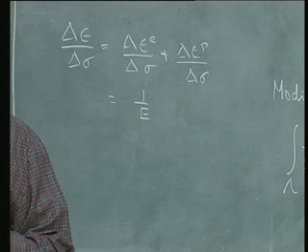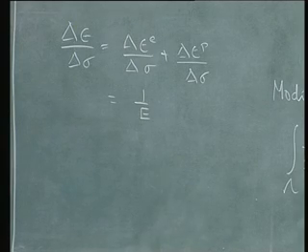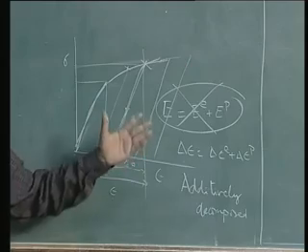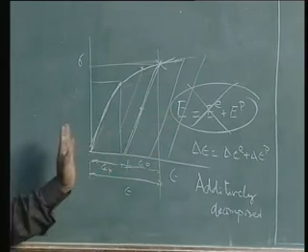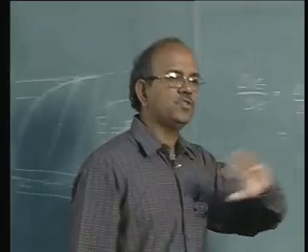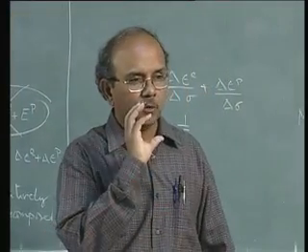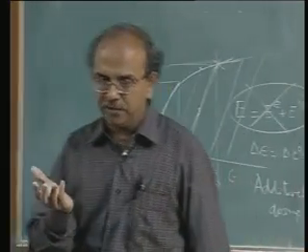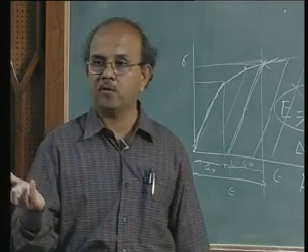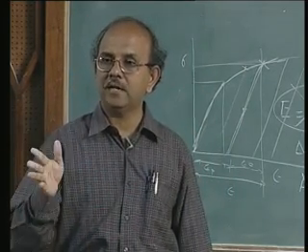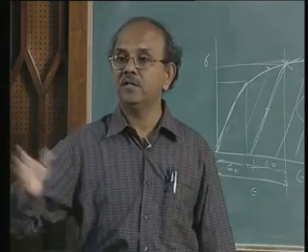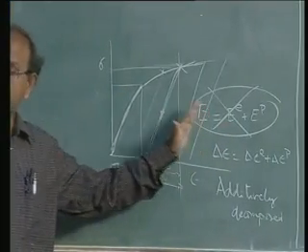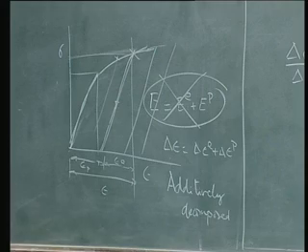A purist may question me. He may say, what are you doing? There may be damage, there may be void formation, there may be other micro cracks that are formed, in which case E may change. You go into an entirely different regime. But for most applications, again we abstract. So we look at the assumption. That's where our engineering judgment comes in. We look at the significance of this assumption for that problem and say that, okay, fine, for this I am okay if I neglect the damage and E is parallel. So most of the time E remains a constant, or in other words the unloading curves are parallel. Is that clear?